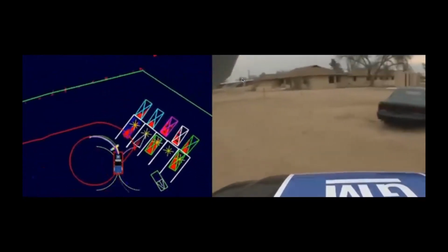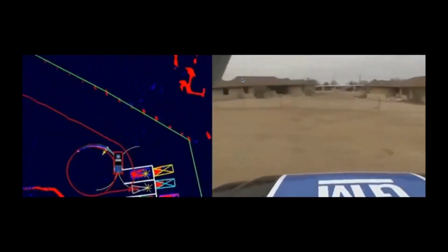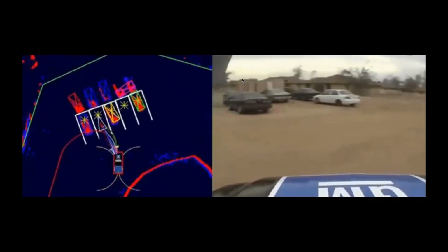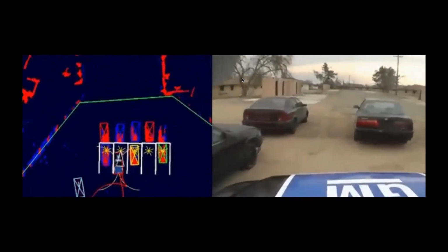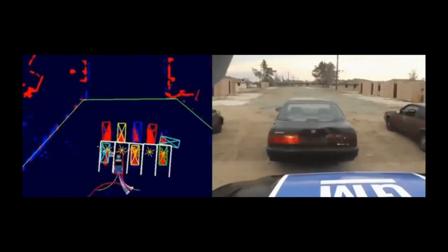I was not involved in the work, but my personal guess is that the number of motion primitives is just not sufficient. So we're now in this very tight spot. They maybe identified an additional obstacle and had to change the plan. And they didn't have enough motion primitives to find a solution that a human would have done, like maybe going just 10, 20 centimeters in reverse and then changing again. And that's exactly the problem with the resolution completeness and resolution optimality.